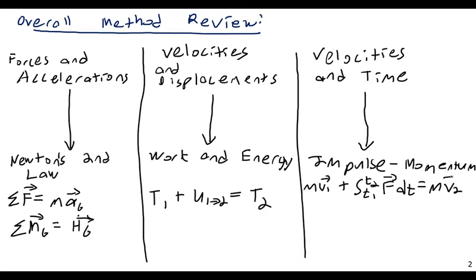Equals mv2. And then in the case of rotational systems, I might say I_G, the moment of inertia about G, times omega 1 plus the integral of the moment from t1 to t2 of M_G dt is equal to I_G omega 2.